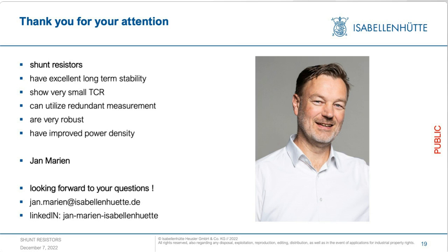What contributes to the temperature coefficient of a battery management shunt? Yeah, basically there are 2 contributions. On the one hand side, it's the material property, and on the other hand, it's the design. I had some examples in my presentation where I showed that the overall temperature coefficient of a battery management shunt is always a combination of the property of 2 materials, the resistance material on the one hand side and the copper on the other side.